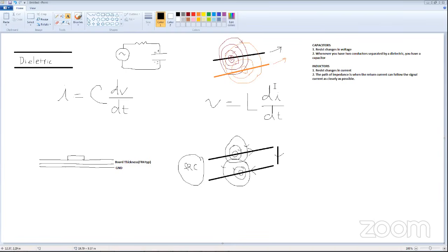So again, you have to look at what type of signal is running through there. If it's not a high-speed signal, if you're not in the hundreds of megahertz, you'll get that scenario that I showed earlier, where the inactive trace shows a couple little blips, but it won't affect your signal much. It won't affect how the circuit behaves. So remember, if you're not dealing with hundreds of megahertz, you're probably okay.